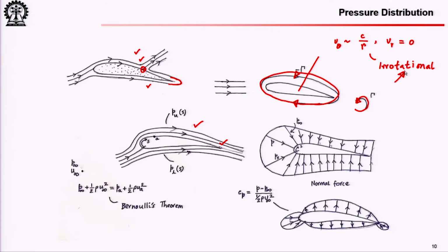Also I said that far from the wing, or a little bit removed from the wing, your flow can behave in an inviscid manner. So, although you have viscosity, the gradients of velocity etc. can be small enough to ignore viscosity. So, in regions removed from the wing surface, I really mean removed from the boundary layer of the wing surface. It is a very thin region. We will talk about what a boundary layer is, what the thickness of a boundary layer is, and what laminar, transitional and turbulent boundary layers are. But you will see it is still a thin region near the wing.